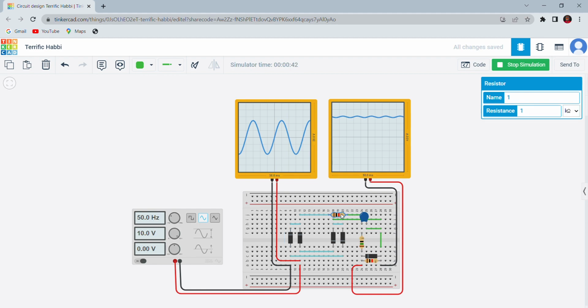After the current flow to the resistor, it will go through capacitor, zener diode, and resistor because as we can see here, we already put it in parallel. And the current will go back to the power supply through the diode 3. This is for the positive charge.